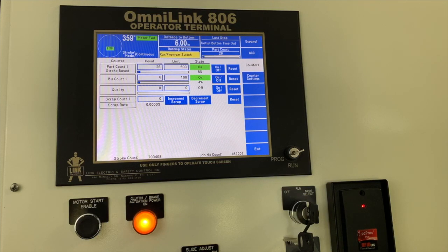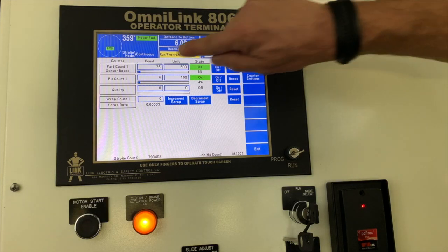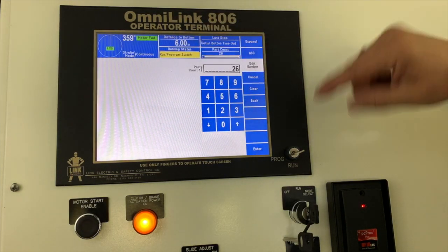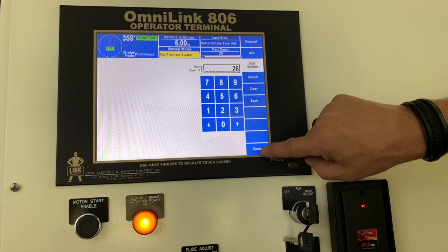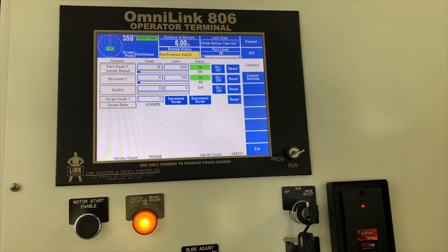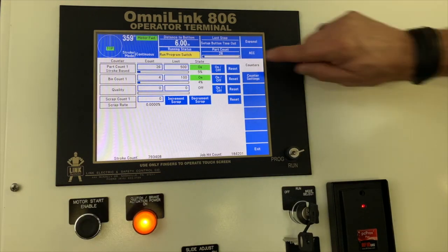If by accident you have cleared the part counter, perhaps in order to run a hot job, you can enter back the number of previously completed parts. Put the count in where it says Count. Part count is the example here. Once you arrive at the count, you will need to reset in order to continue. Confirm Yes.